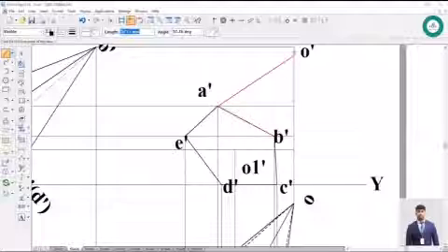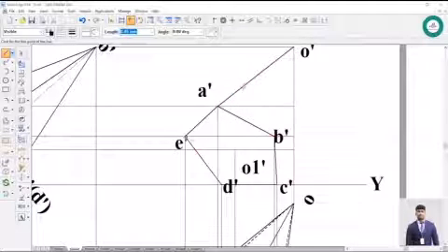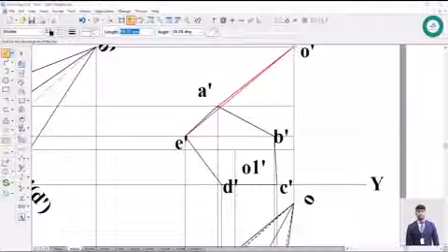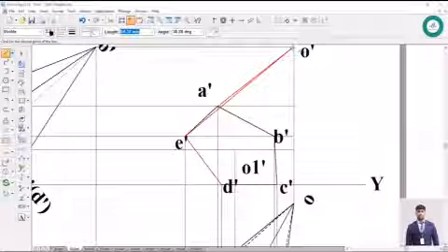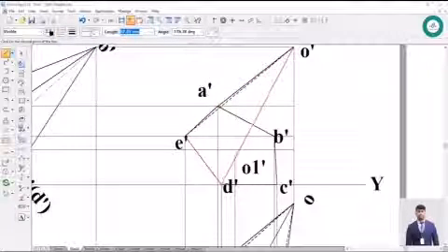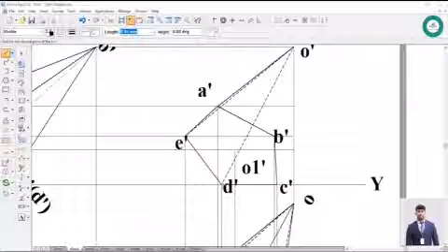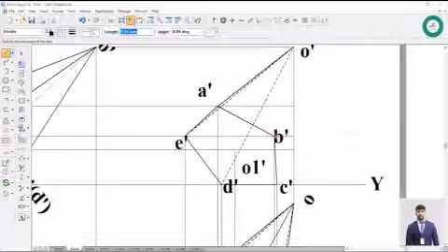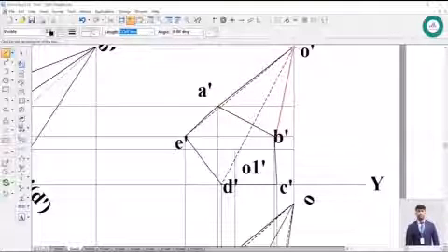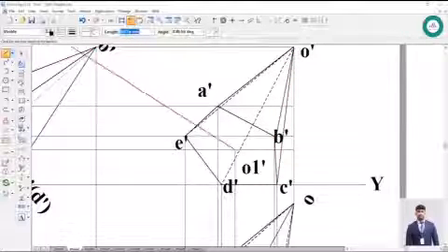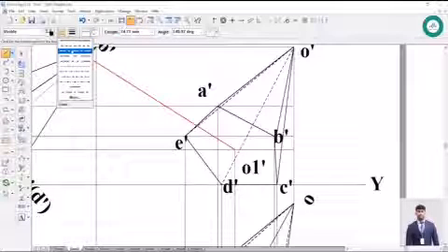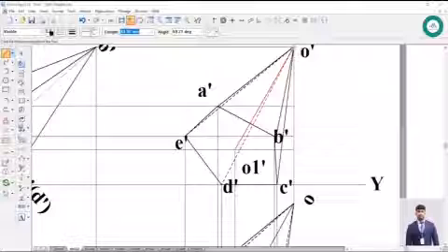A is just emerging, so this is continuous. But when I take this point E, you can see it is dividing the base. So you can make this a dotted line. And again, this D is also dividing. It's supposed to be a dotted line. Next, B point is just emerging. It is continuous. And C is also just emerging. It is continuous. Next, from O to O1, take the suitable axis line and its least size. So by joining all these things,